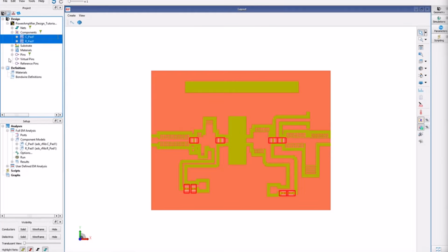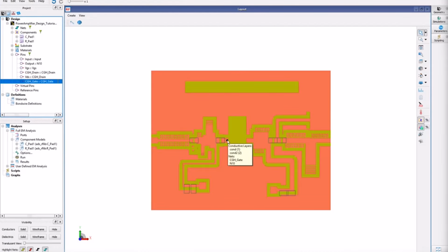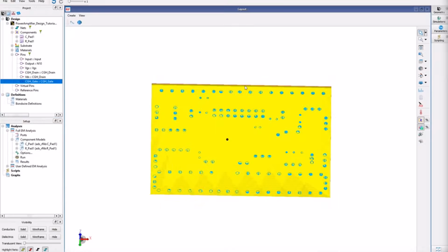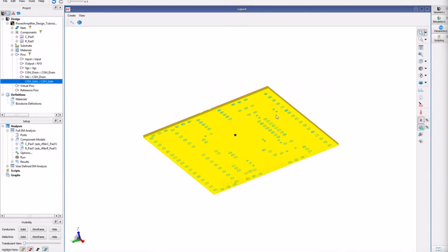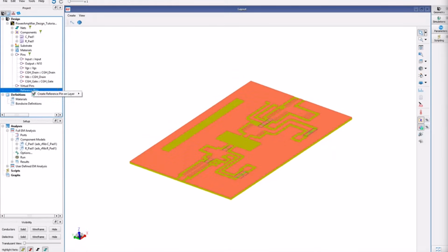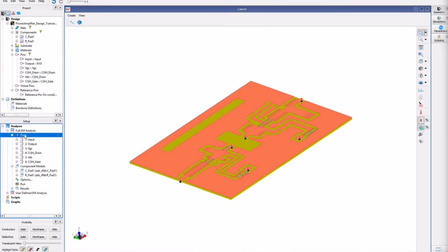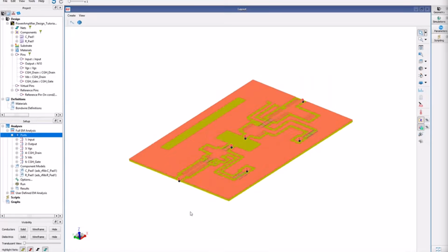As simple as that. Okay, I have these pins, as you can see, input, output, gate bias, drain bias. This is gate, VDS, and that's your gate for the device. So I have these many pins. You need to create a port. You first need to explain where is your ground, right? So this contour is going to be your ground. Simply define that, hey, my reference is contour. And that's it. Now you can simply drag and drop. And now, bang, you created so many ports immediately.